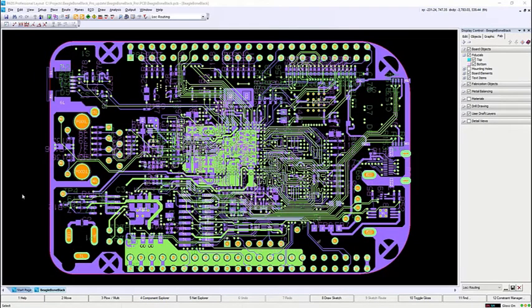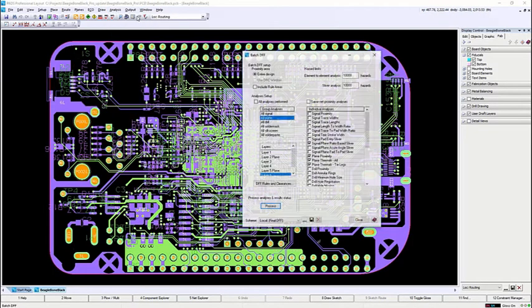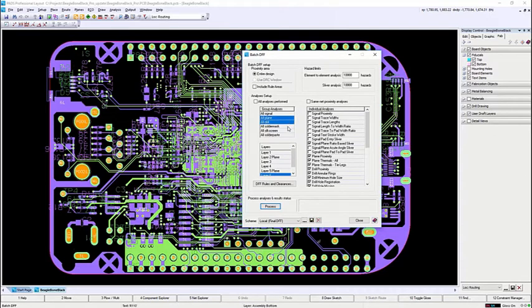Design for Fabrication Analysis, or DFF, enables you to find potential fabrication errors before you generate manufacturing output data files. You can check for same net layout problems such as acute angles, potential slivers, and acid traps. At different design phases, different DFF analyses are recommended. In the post-placement phase, proximity of components is key to focus on. Analysis during post-routing should also include all planes, solder mask, and solder paste. Once the design is finalized, a full batch DFF analysis is recommended.